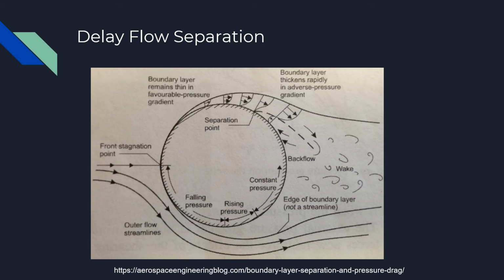The flow separates when the boundary layer grows big enough that the deceleration reverses the direction of flow near the surface. Because of the shape of the laminar velocity gradient, laminar flow separates easily, while a turbulent layer can grow much larger before the reversal and separation. By creating a turbulent boundary layer, friction drag is increased, but the flow can stay attached longer, decreasing the pressure drag. For a bluff body, this exchange is worth it.